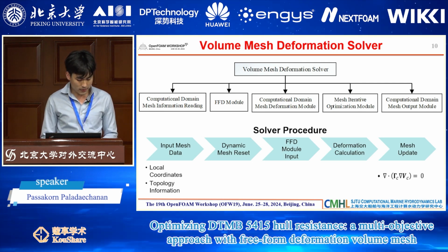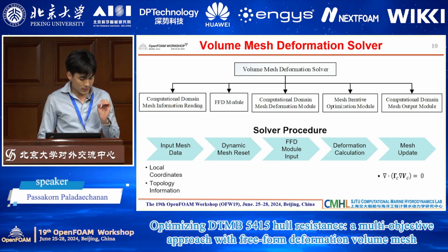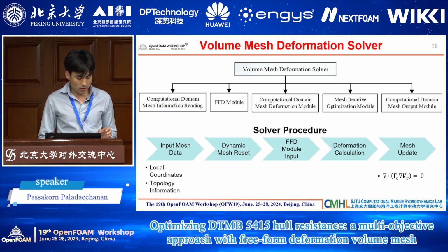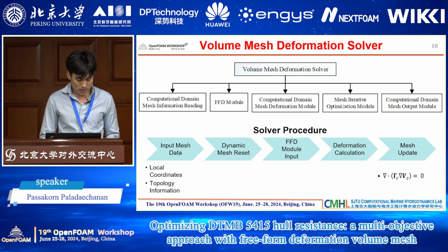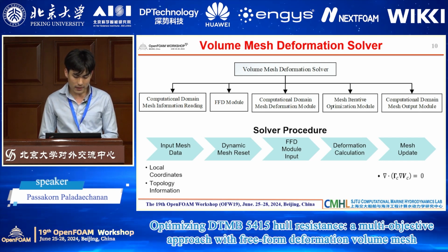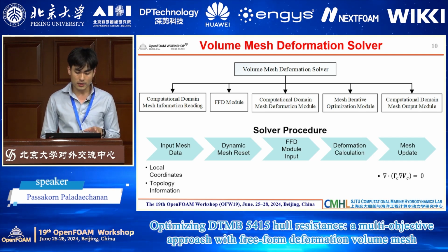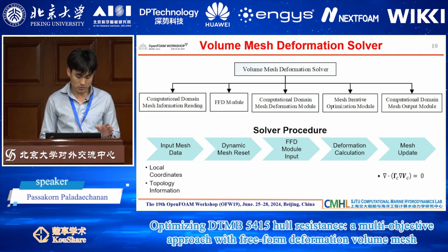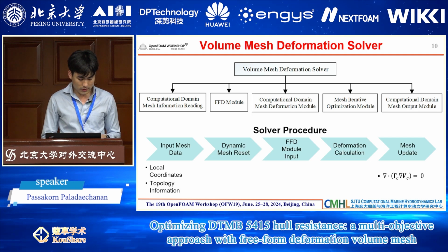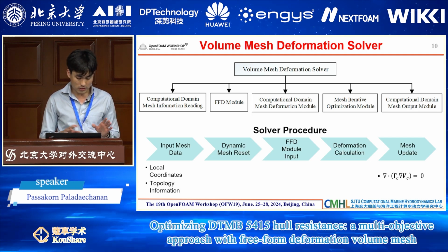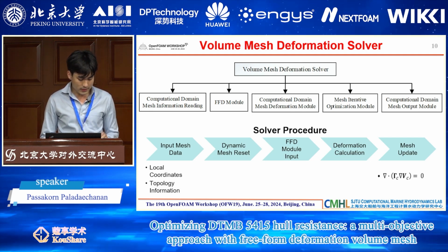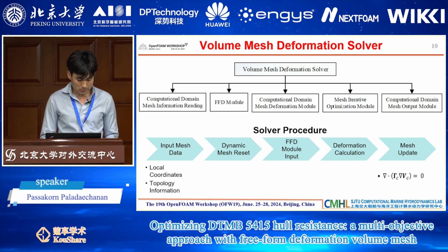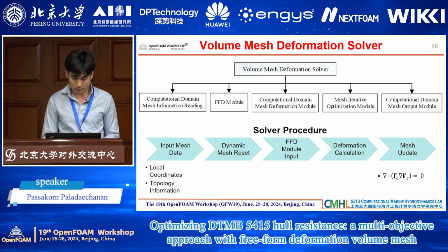After that, we utilize the dynamic mesh technique, so the coordinates of the structure boundary mesh are reset. Then for the freeform deformation module input, the reset structure boundary mesh points are input into this module. Within this module, the coordinates of the structure boundary mesh points inside the lattice are computed based on the structure boundary mesh points and lattice position information.